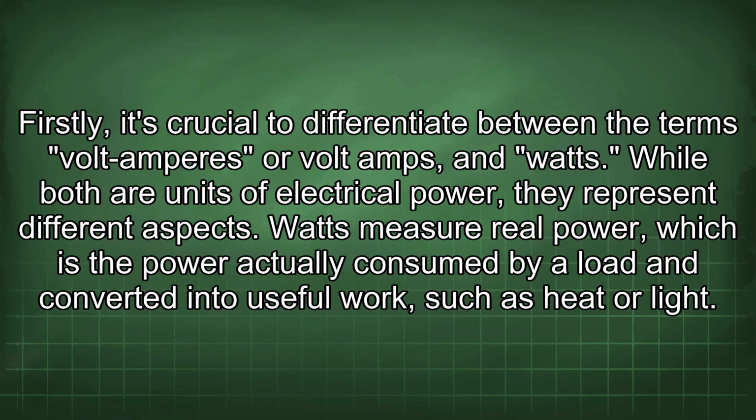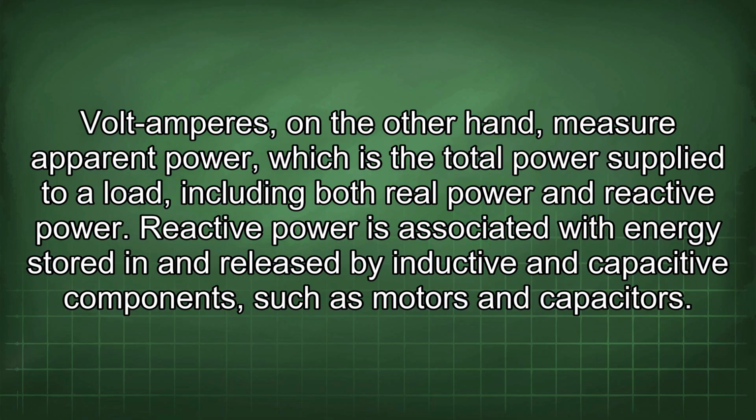Firstly, it's crucial to differentiate between the terms volt-amperes or volt-amps and watts. While both are units of electrical power, they represent different aspects. Watts measure real power, which is the power actually consumed by a load and converted into useful work, such as heat or light. Volt-amperes, on the other hand, measure apparent power, which is the total power supplied to a load, including both real power and reactive power. Reactive power is associated with energy stored in and released by inductive and capacitive components, such as motors and capacitors.